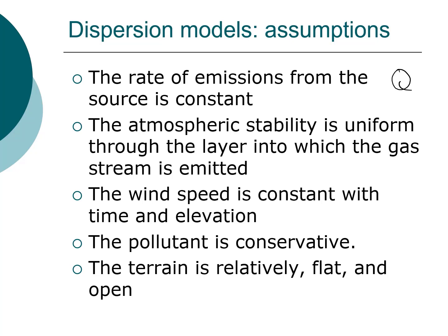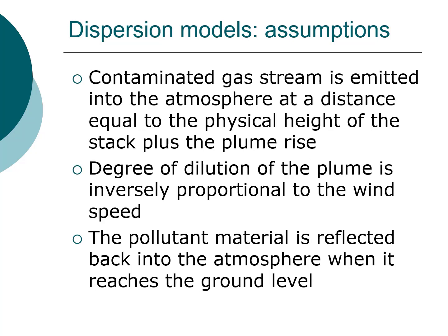The terrain is relatively flat and open. Also, the contaminated gas stream is emitted into the atmosphere at a distance equal to the physical height of the stack plus the plume rise. And we refer to that as the effective stack height. The degree of dilution of the plume is inversely proportional to the wind speed.